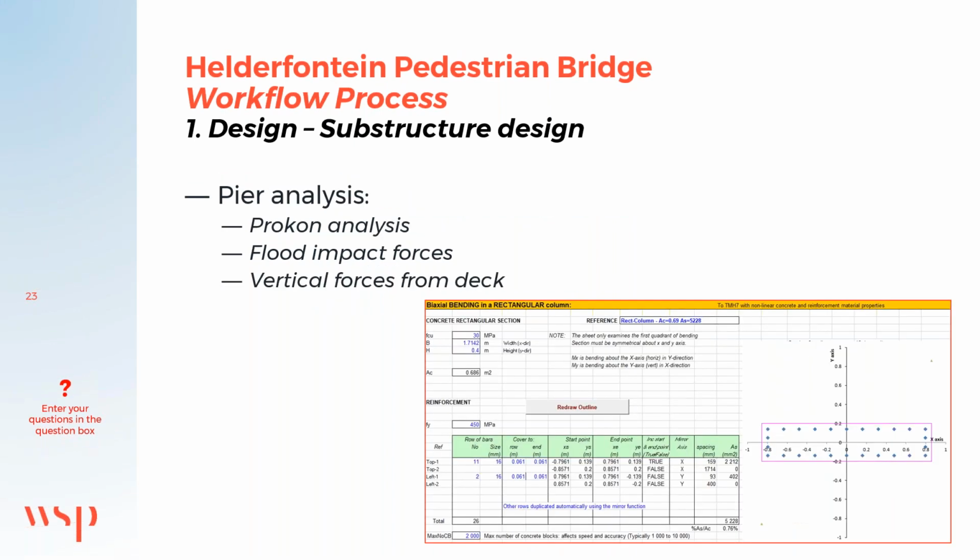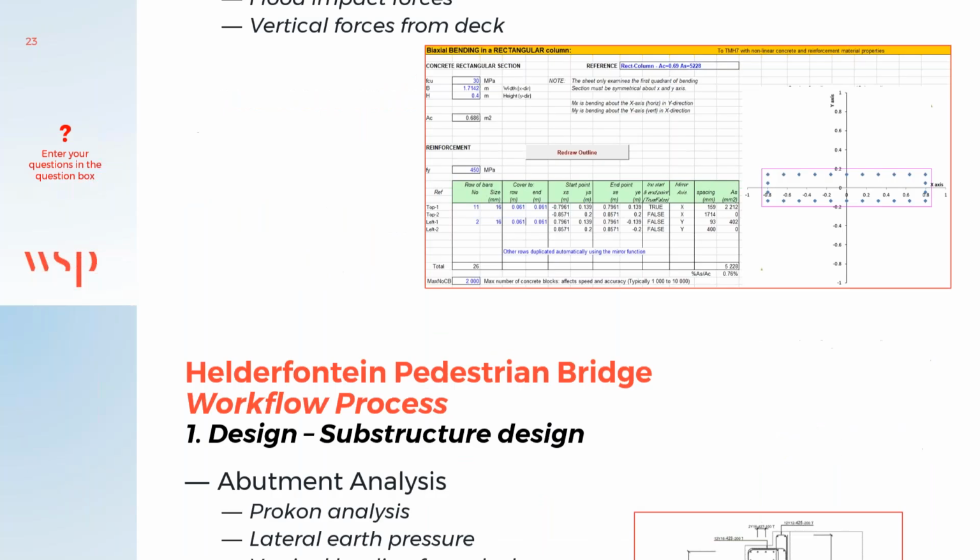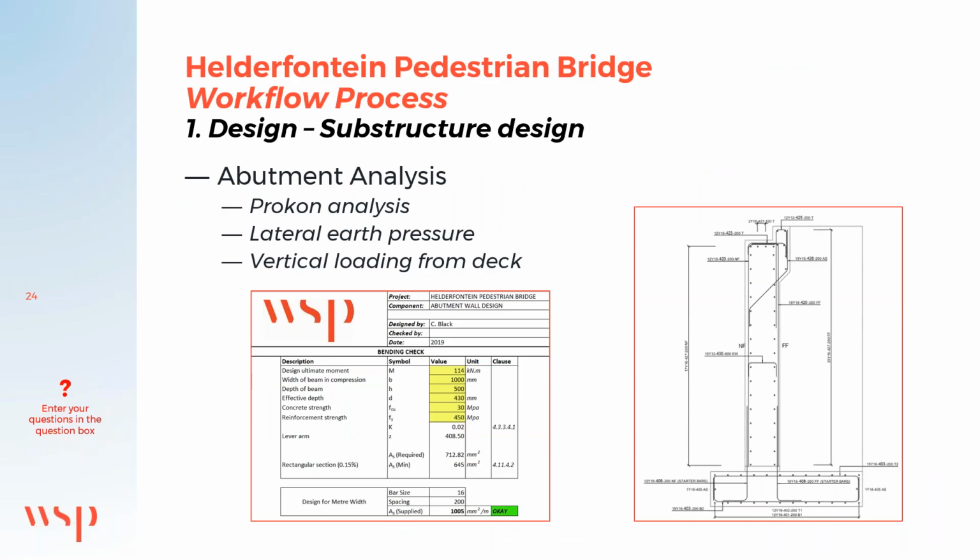For the pier analysis, we utilized Procon analysis, considering flood impact forces as well as vertical forces from the deck. For the abutment analysis, we also utilized Procon analysis, considering lateral earth pressure as well as vertical loading.